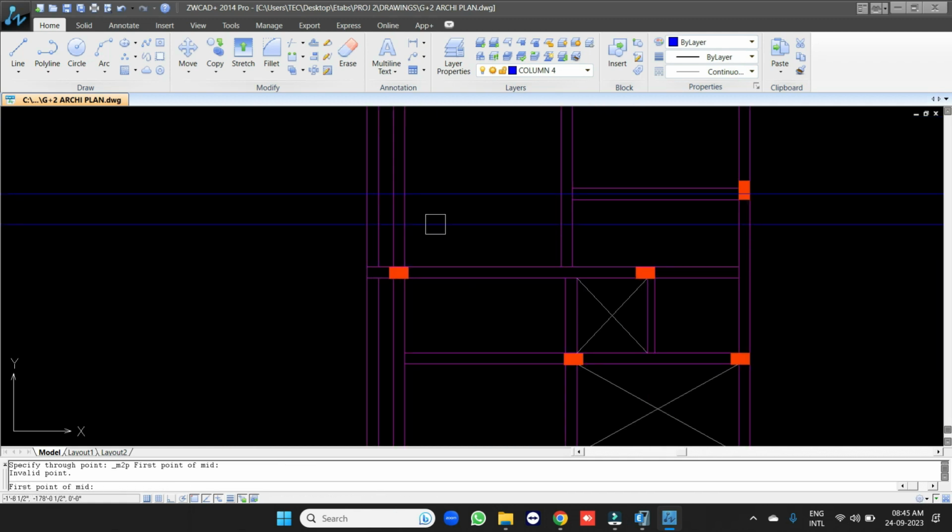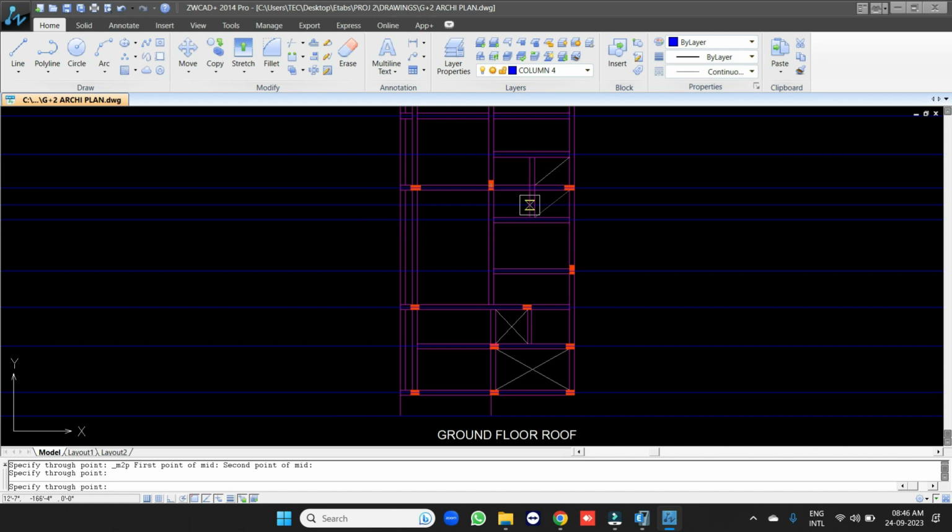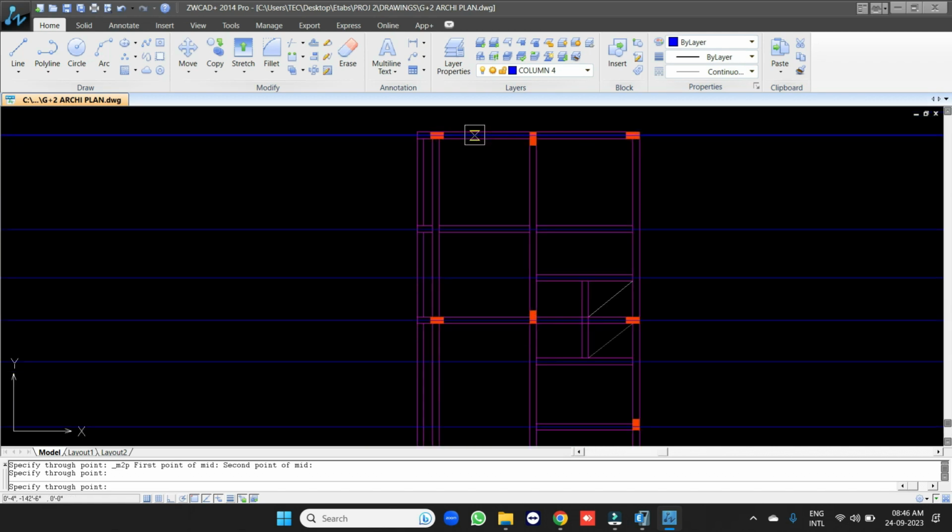The structural engineer should have minimum knowledge of AutoCAD to access the AutoCAD file. Here it is a balcony and it is only one line, so I prepare the line here. So all the horizontal beam center lines I have marked, and then similarly let me mark the vertical direction beams.